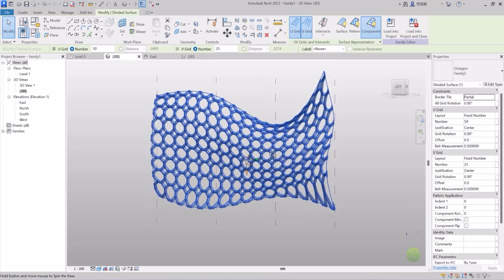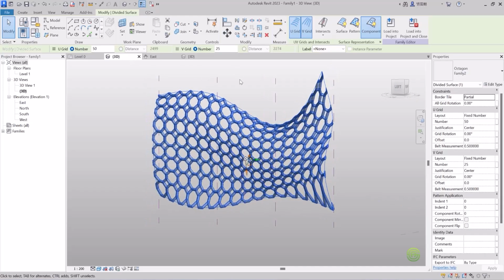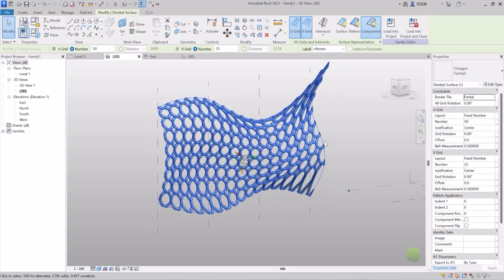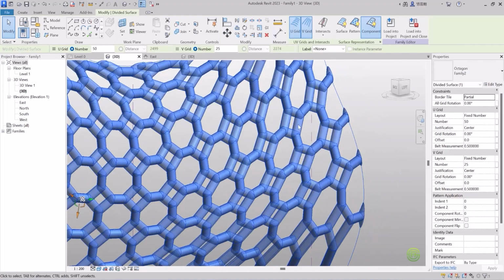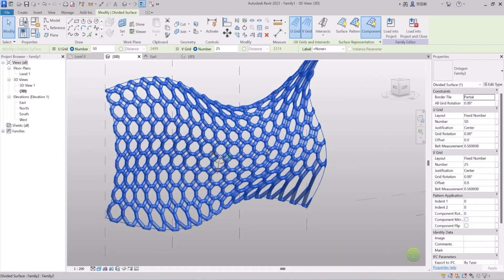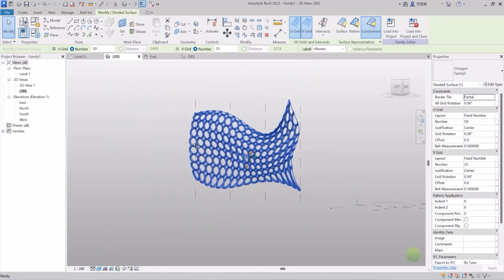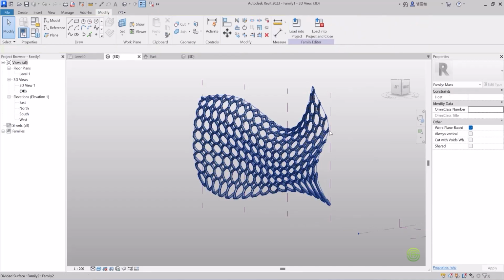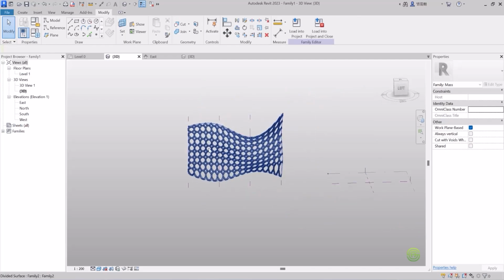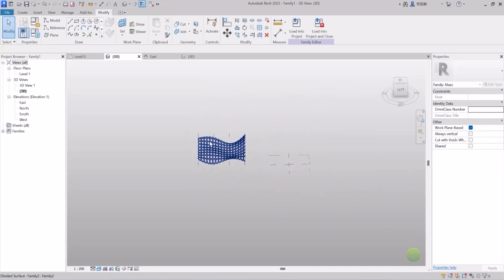So the thing is, you have to give the proper dividing surface, and after that we also have to make sure our thickness is proper. Here the thickness is more. We have to reduce the thickness in the curtain panel pattern first. There we should reduce the thickness a little bit, then it will look really nice. So like this we have to give a thickness to this kind of surface. I hope you guys understood this. We can make many more patterns like this. So we will create another thing also.